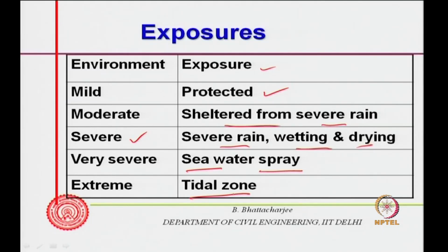For seawater spray, within 5 to 10 kilometers of marine sources, there can be chloride accumulation, because aerosol formation can occur at the crest of the wave. The salt can go into the air, and due to wind it might migrate inside. Some zones close to the seashore will be quite severe if there is water spray simultaneously.